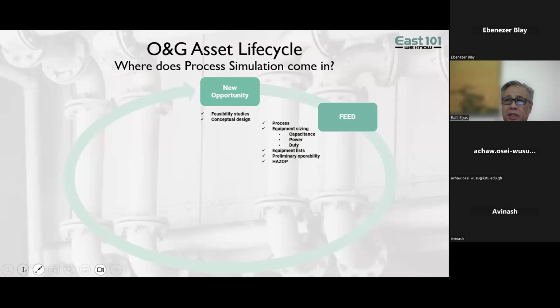You need some hydraulic calculations to check to make sure that your trays aren't going to be flooding. Make sure that you've got enough hydraulic behavior in your trays to avoid your flooding or weeping, etc. So you'd be using some simulation. You'd probably still be using some kind of steady state simulation tool, maybe with some slightly more sophisticated equipment based modules or third-party modules. You might also be doing things like HAZOP at this point in time.